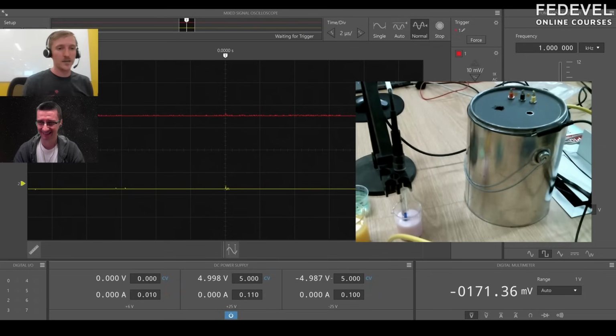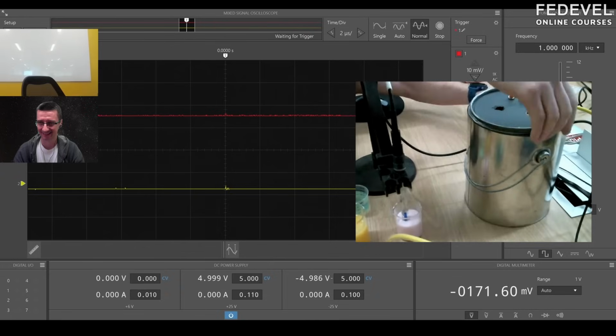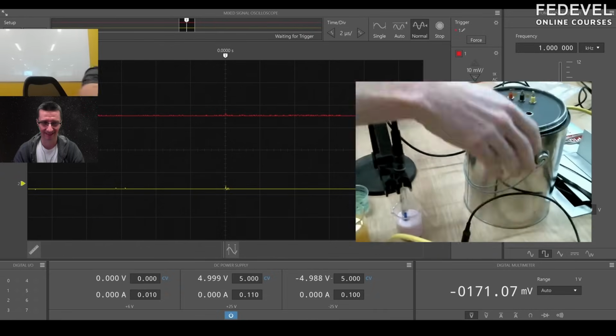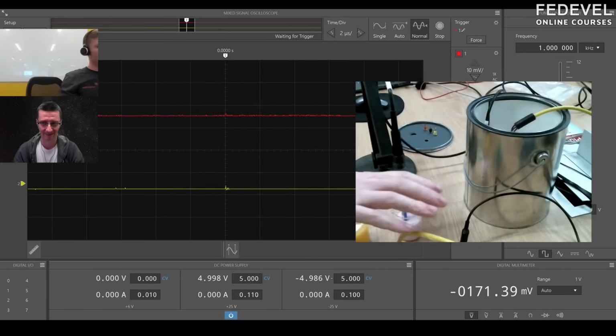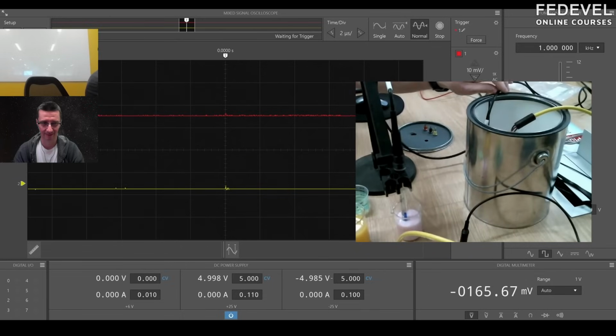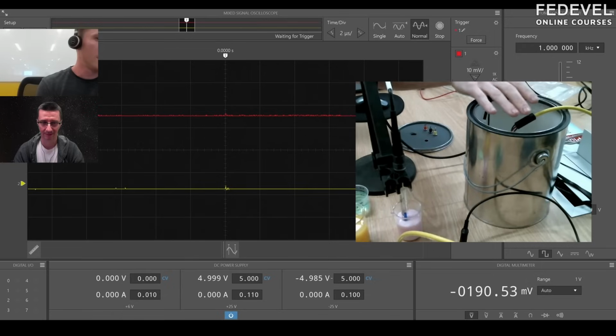So this is a very good shield connected to ground. But you'll see what happens if I actually remove the ground connection and I leave this tin can floating. So we have 2 ground connections here. I'll just remove both of them. And now all of a sudden, if I wave my hand around the assembly, we can see our voltage is changing very drastically. If I wiggle these cables here, the voltage is going all over the place simply because of capacitive coupling. Even just my body has a charge to it. It has a very small magnetic field. And bringing this into close proximity, it's going to couple into the signal because it's such a high impedance.